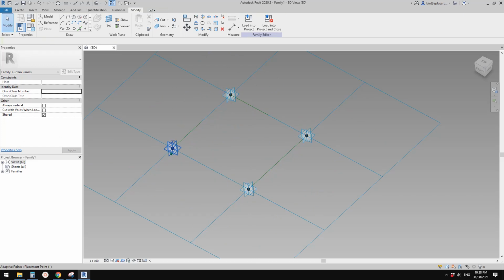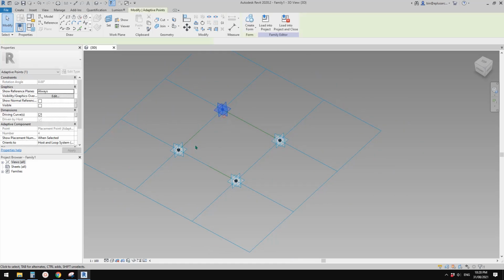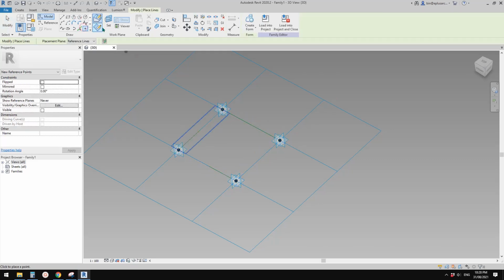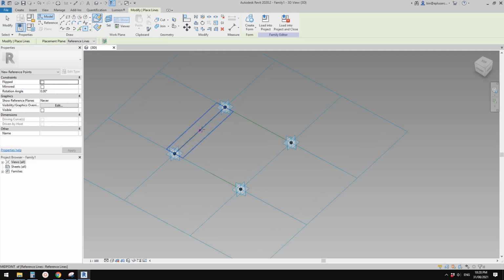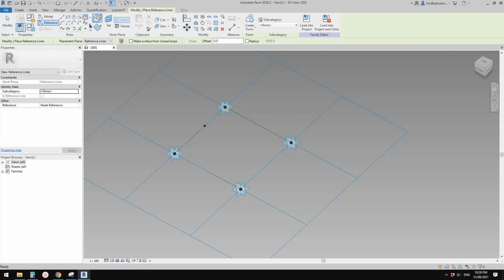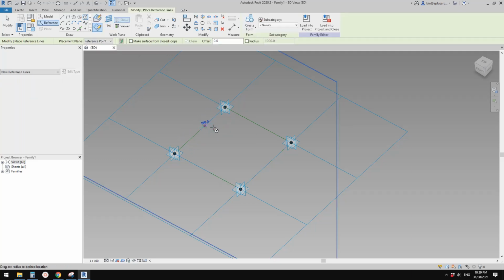Let's just have a look. I don't think it matters, so we can just select one. First, I'll place a point, draw on face. Draw on face and anywhere on this reference line, and then use reference line, draw a shape. I'm going to use this circle, draw on work plane, set work plane, pick the vertical work plane of this point and draw a circle and create a radius parameter.